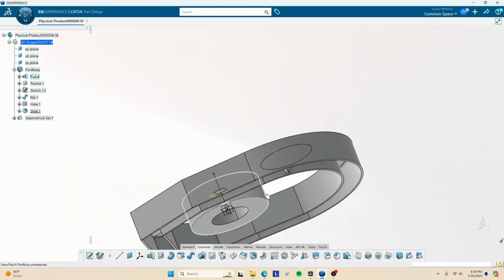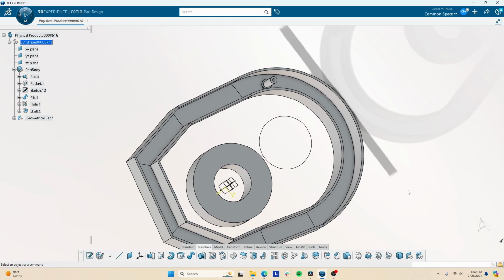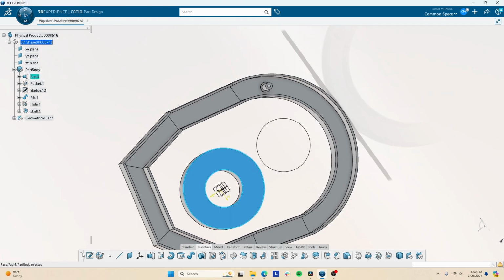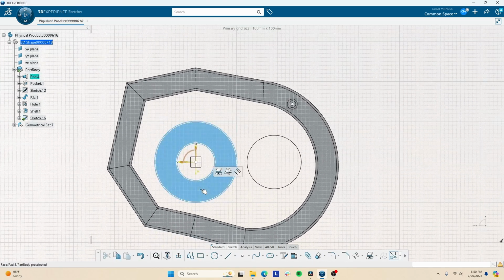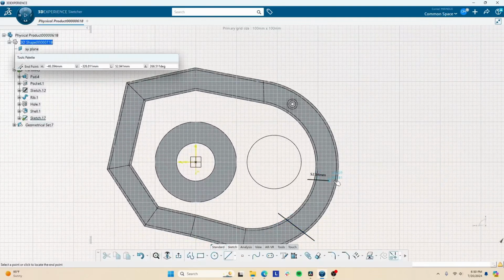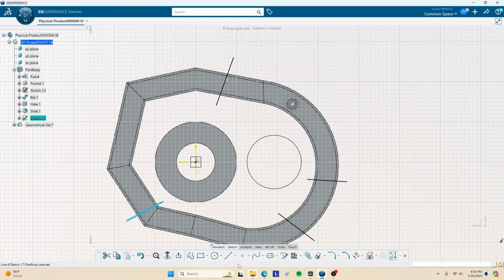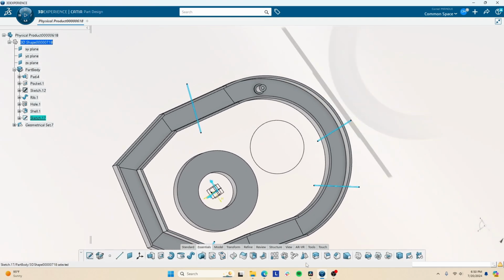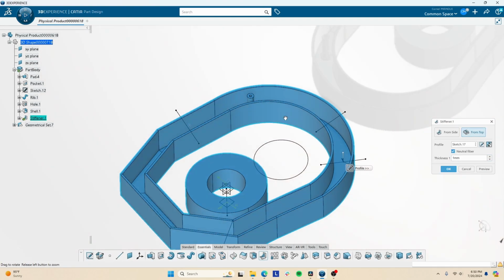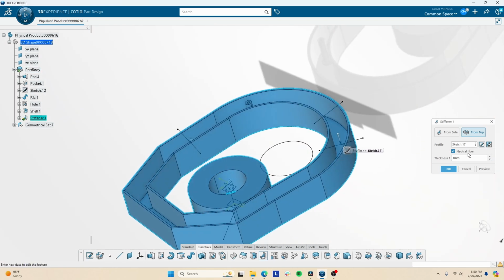Let's, in this case, create a stiffener. There's two ways you could do this. Let's do one from top over here. If I want to create a sketch here, for example, then let's do that. I'm gonna exit. There's a sketch here. Let's make some lines here. Exit. If you want to create a stiffener based off that, it will be from top and it will go down. It sort of knows already where it should project to.